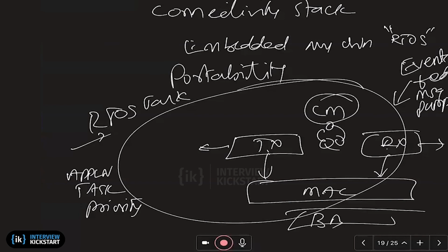Then you have other mechanisms like producer consumer, and some RTOSs give you all this, such as the priority inheritance protocol, so you don't hold a resource and then priority inversion happens. Those are all sophisticated, advanced things that you use in mission critical systems. Some may give you monitoring features, some may give you deadlock avoidance features. So it depends on your needs technically.